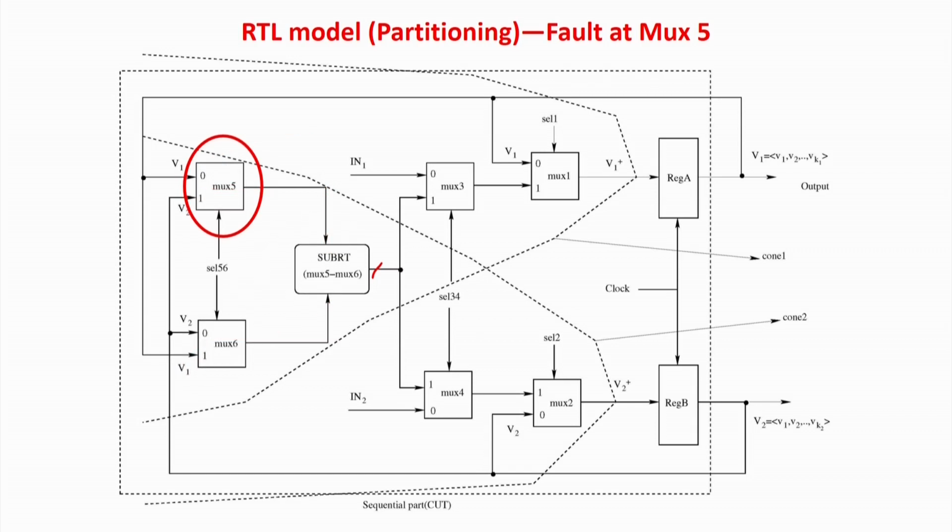So you can easily appreciate that because of this crisscross fault, this is basically a cross fault. What is going to happen? I am going to have the answer here as V1 minus V1, or V2 minus V2, instead of V1 minus V2 or V2 minus V1. So that is the problem that is going to happen, and that is actually the fault over here.